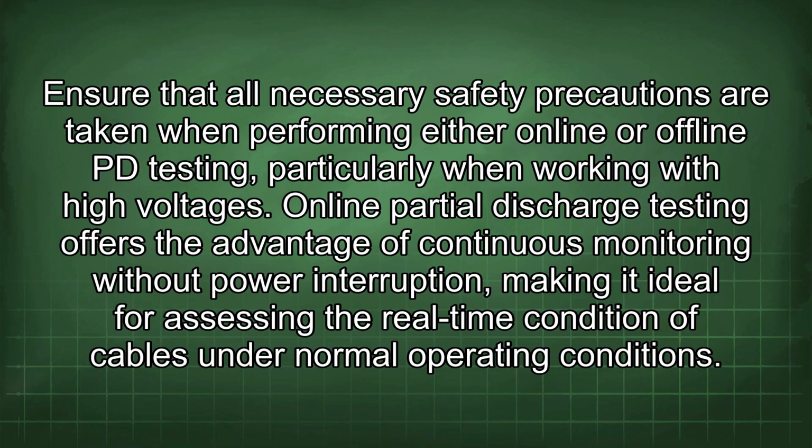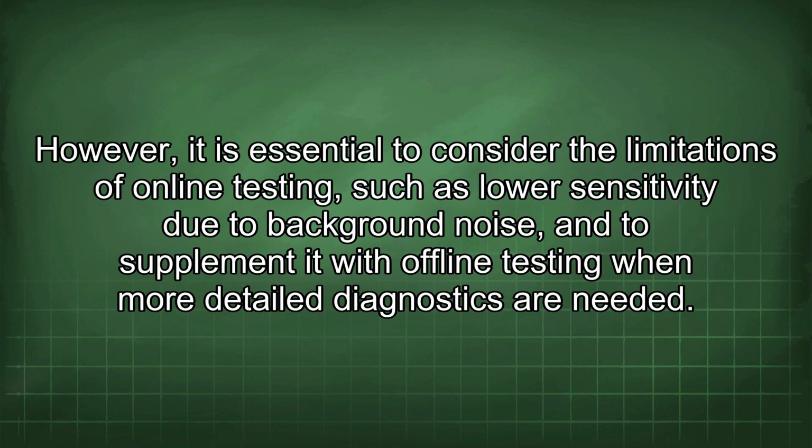Online partial discharge testing offers the advantage of continuous monitoring without power interruption, making it ideal for assessing the real-time condition of cables under normal operating conditions. However, it is essential to consider the limitations of online testing, such as lower sensitivity due to background noise, and to supplement it with offline testing when more detailed diagnostics are needed.